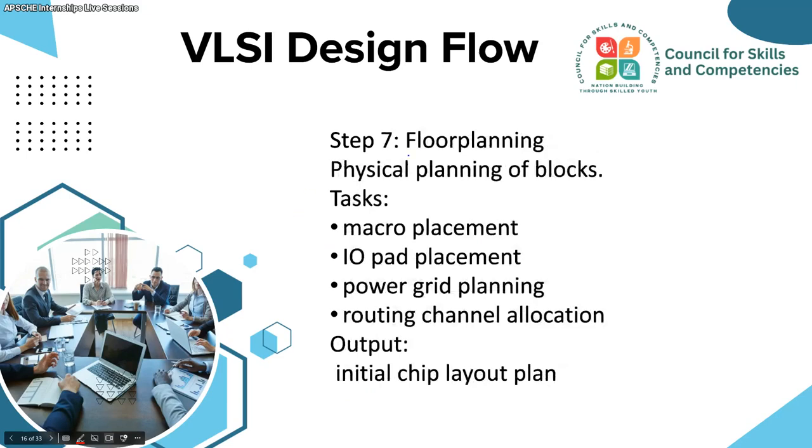And then floor planning, it is the actual physical stuff. It is the physical planning of the blocks. The tasks are that we have to place the macros, input output pad placements, the power grid planning, and the routing channel allocations.